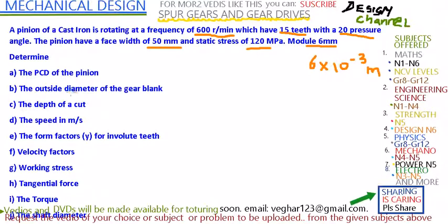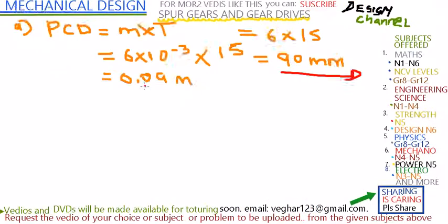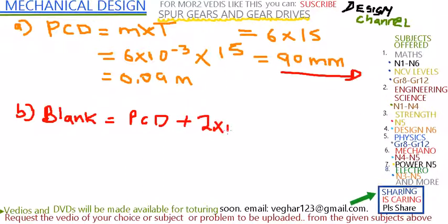Okay. The outside diameter of the gear blank. To calculate the outside diameter of the gear blank, use the formula which says PCD plus 2 times the module, which is 90 plus 2 times 6.